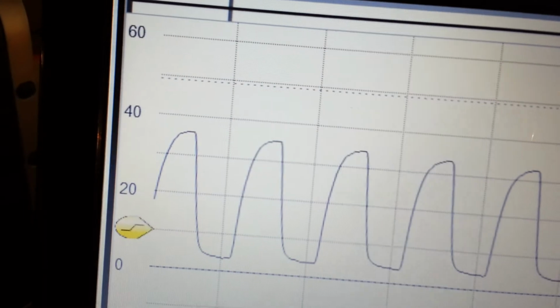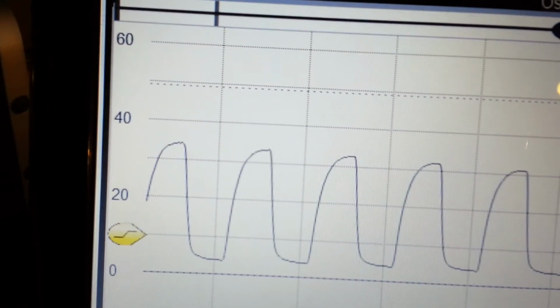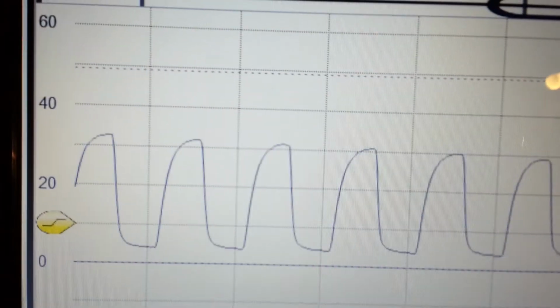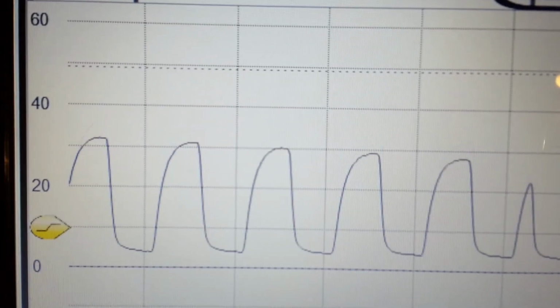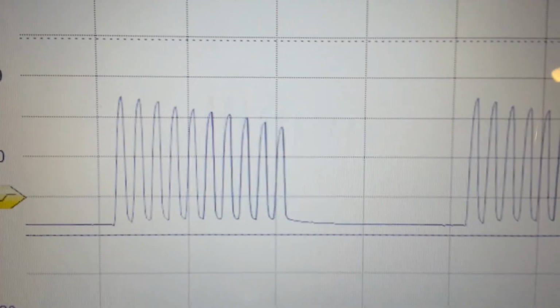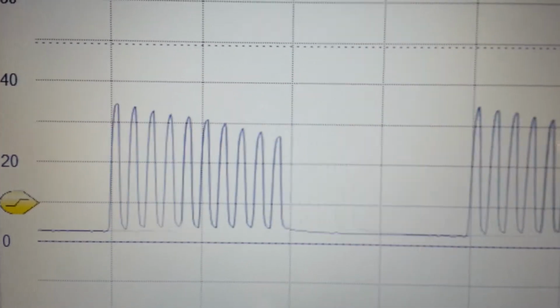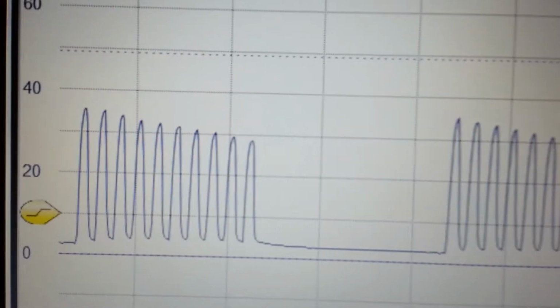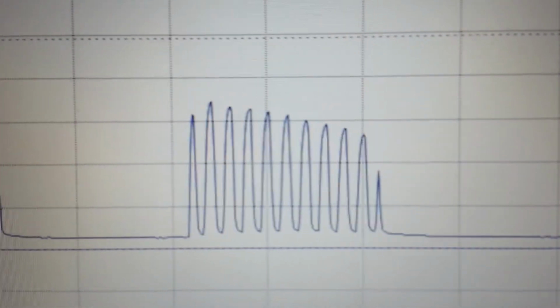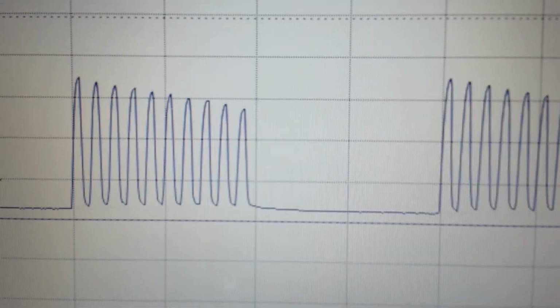Without chokes, you do not get the step charging effect, and you also don't get the frequency doubling effect, which is really the incorrect term. Stan Meyer calls it frequency doubling, which it does not do. It doubles the pulse length. It takes it from 50% duty cycle to 100% duty cycle.